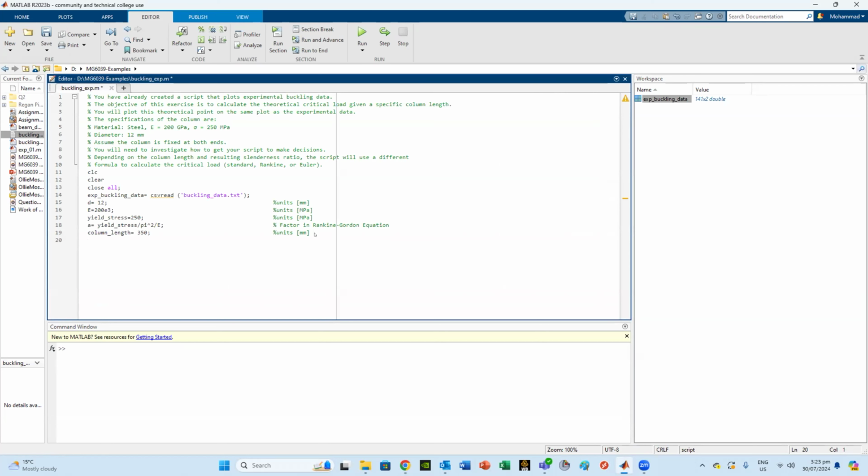All right, so now we need to find the effective length, or LE. So I'll call it LE at this stage. And LE equals, for this case, 0.5 times the column length, because that effective length, I'll write the comments here, we call it effective length for us.